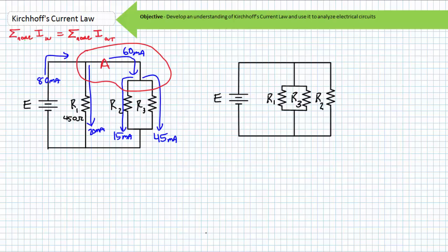You can group R1 and R3 together and put R2 on the far right. Now incoming current splits into two paths. The first path being the current intended for both R1 and R3. The second path being that intended for R2. The first path is then again subdivided between R1 and R3. You are only limited by your creativity in arrangement, rearrangement, redrawing, and simplification of parallel networks.